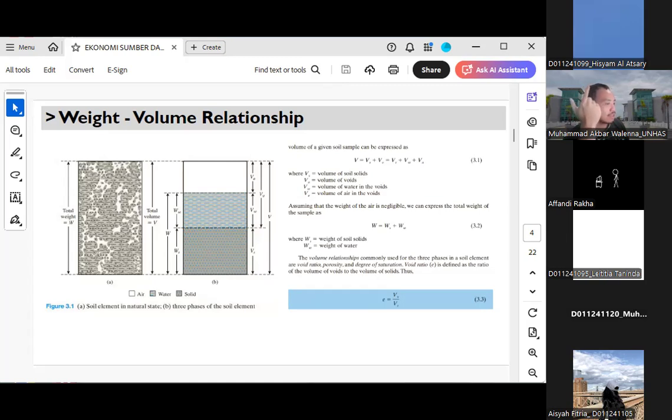If a soil has a high void ratio, that necessarily means that there is a lot of empty space relative to the solid particles. It means there are more spaces available to be occupied by water or air, in comparison to the amount of space occupied by the solid particles, or the soil grains, itself.